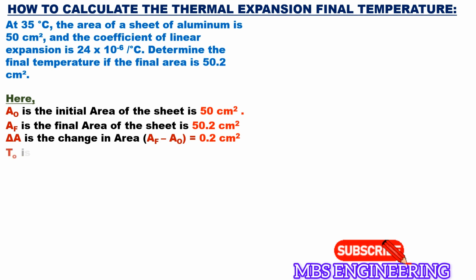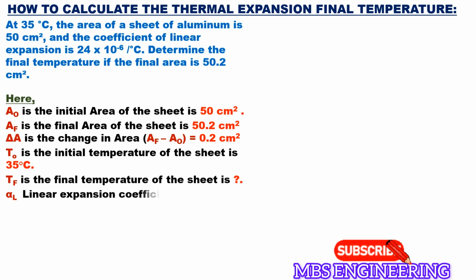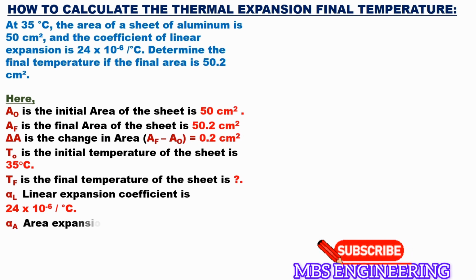Next, T0 is the initial temperature of the sheet, which is 35 degrees Celsius. Next, TF is the final temperature of the sheet, we need to calculate it. Alpha L is the linear expansion coefficient, 24 into 10 power minus 6 per degree Celsius. Next, alpha A is the area expansion coefficient for the sheet, we need to calculate it.